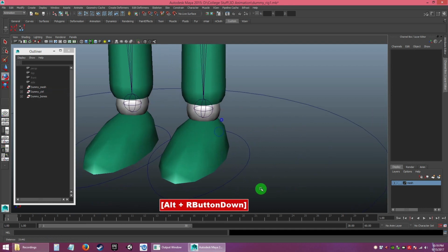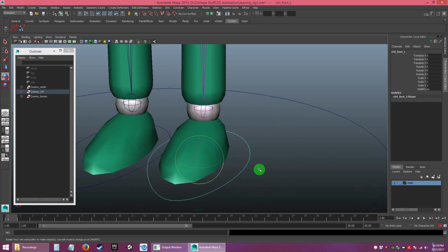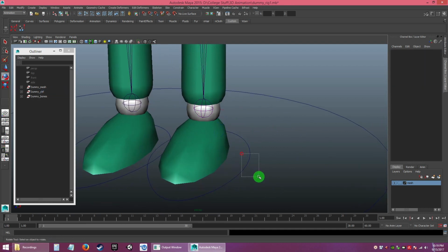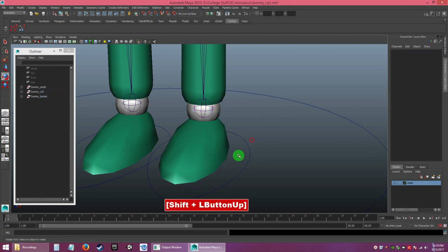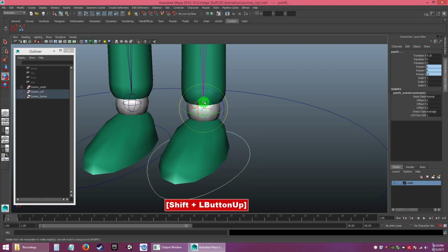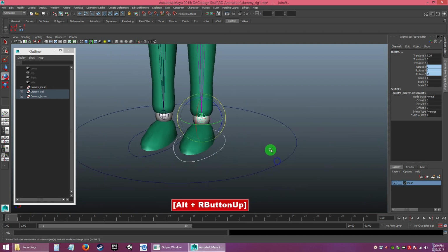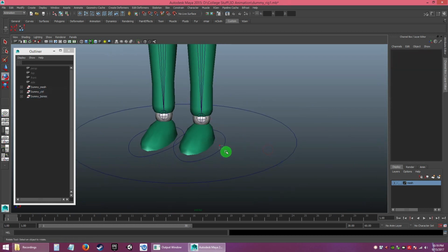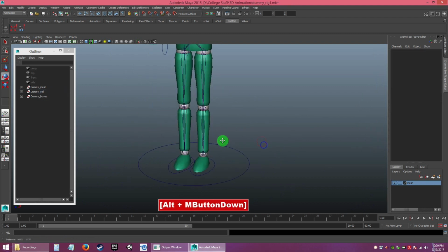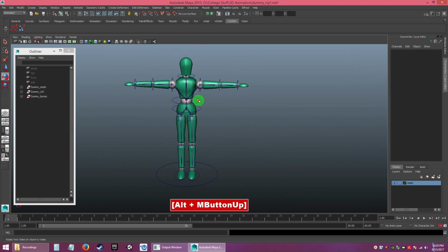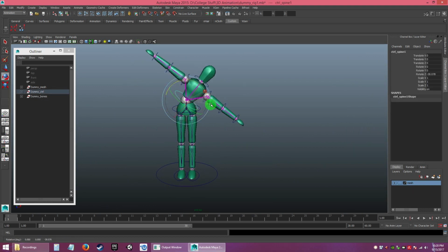That's why you constrain the foot controller, and you constrain the ball joint here. I used the orange constraint just now, so that's the reason why you can control rotation on the foot. Okay, so I think everything should be fine.